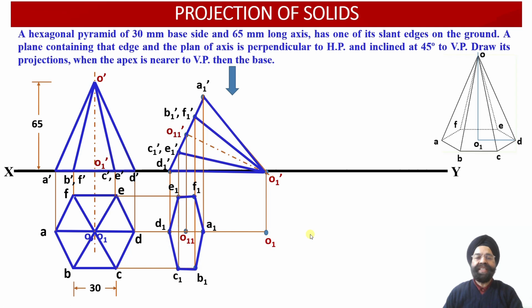Now we have just discussed that all the edges joining D1 should be drawn as dotted, but we have joined D1 E1 dark, we have joined C1 D1 dark. Why have we joined these two edges dark? Because these two edges are constituting the boundary of the solid. And moreover, as the observer is going to look at the solid from this side, this outline of the hexagonal base, this entire base, will be visible to the observer. So this is falling in the boundary, so that is why it will be visible to the observer as well.